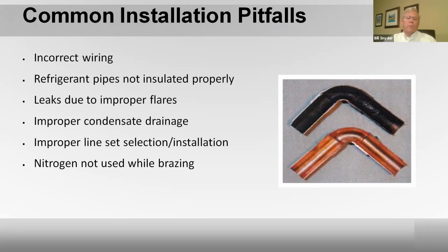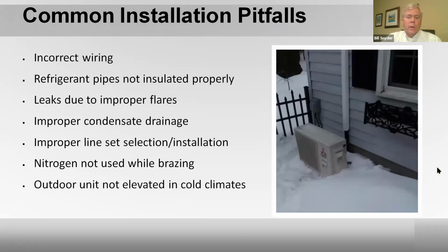If it plugs up, you'll probably find, if you follow the tubing along, a little area that's frosting up in the tubing because there's a restriction there, or you can physically feel a temperature difference. You would have to cut that out and find a strainer and try to fit it in there, which in this equipment, there's not a lot of room to work, so that could be a problem. So if you have good installation practices and use nitrogen, you'll have a nice shiny fitting like this. You won't have an issue.